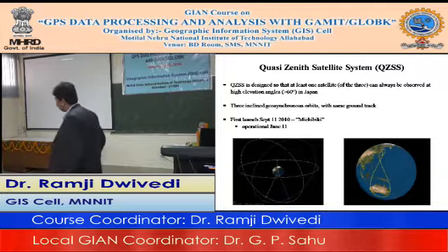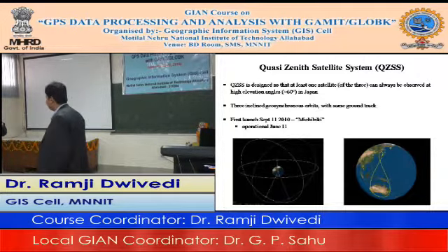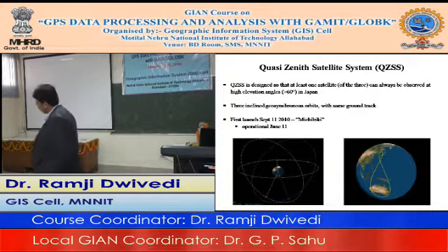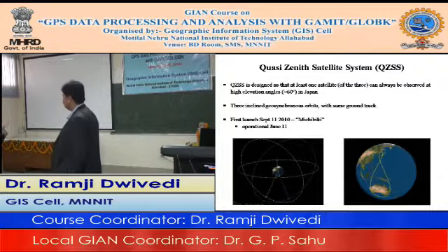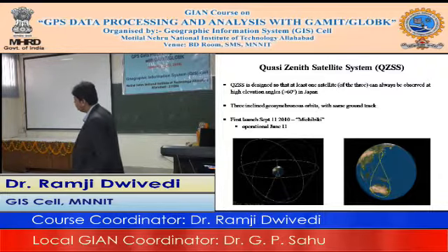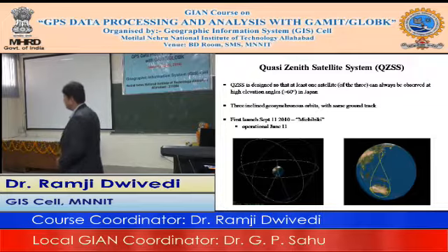But these days, when you have so many satellites in orbit, we were talking about you definitely need at least 4, but now most of the time you have 10 to 12 satellites visible, and that extra redundancy in the data makes this all happen much faster. They're all basically kinematic, Kalman filter-based approaches. I think the only distinction of on-the-fly was they were doing the processing with a Kalman filter rather than with a weighted least squares approach. But again, these tended to all be proprietary terms, and these days it's all very much just real-time kinematic, where you can move around and the receiver tells you how you can do it.